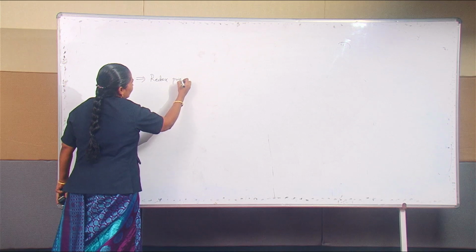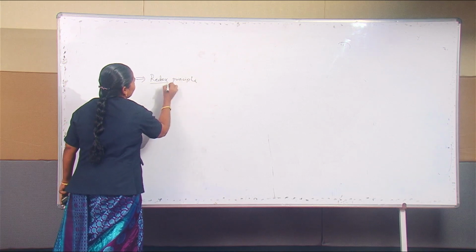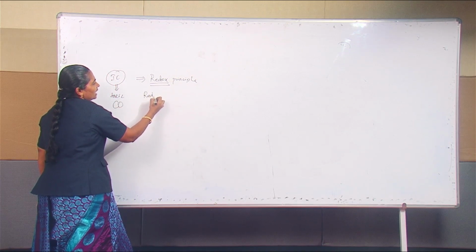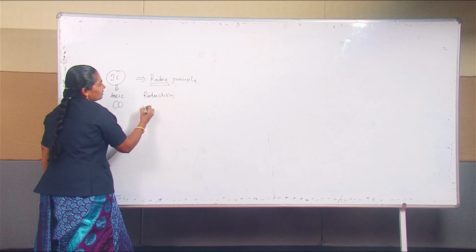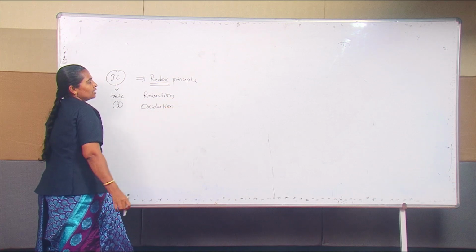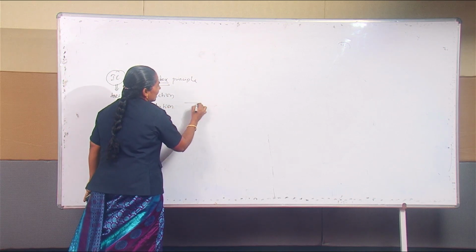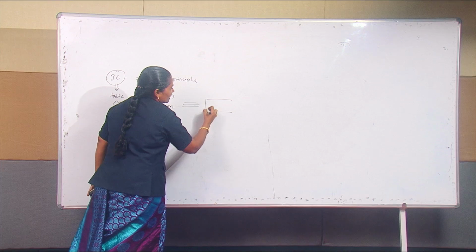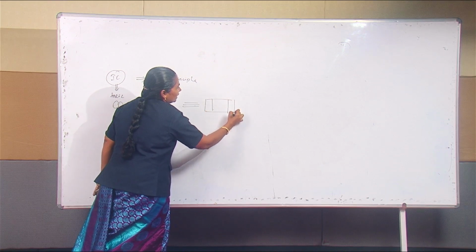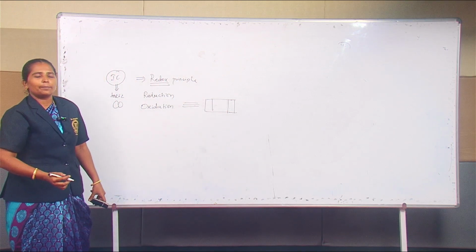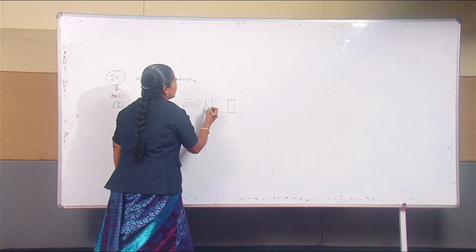So in this chamber, redox reaction will be taking place. The redox reaction means nothing but reduction as well as oxidation will be taking place to remove the unwanted toxic material. So in this chamber, the exhaust gases will be going inside to the particular chamber. In the particular chamber, there will be two compartments. One compartment will be undergoing reduction reaction. Another compartment will be undergoing the oxidation reaction.